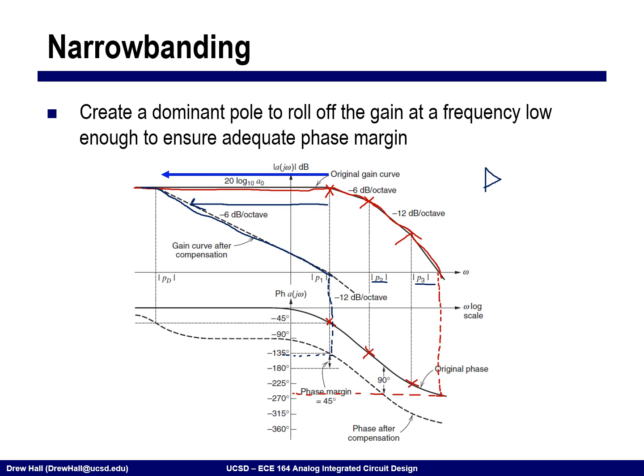Let's take our folded cascode amplifier, and rather than draw this all out, I'm going to simply write that this is a folded cascode. Okay, so I have my differential inputs. The way that I'm going to compensate this is by adding an output capacitance.